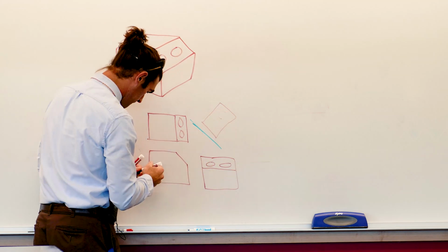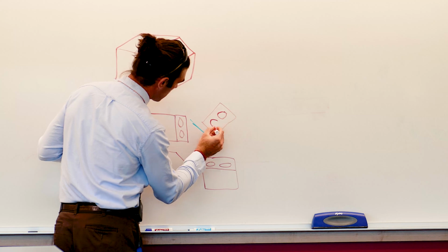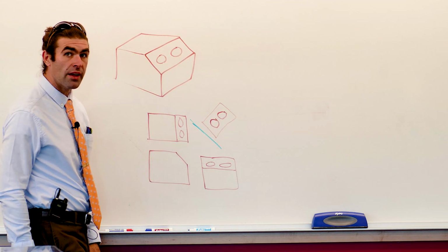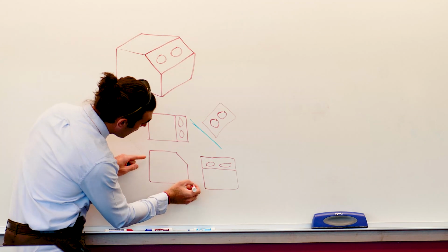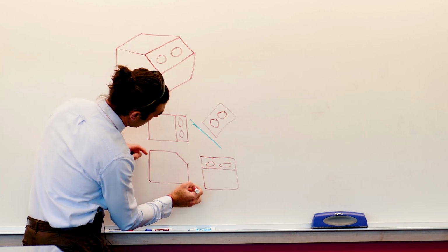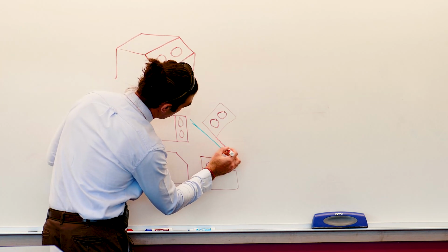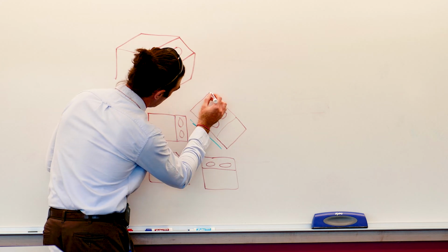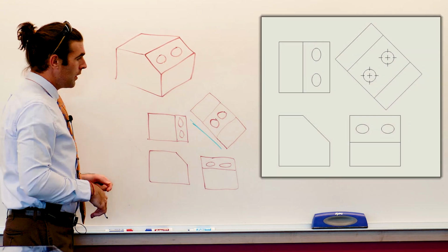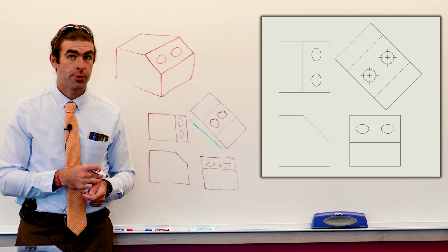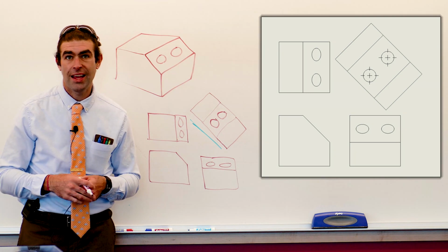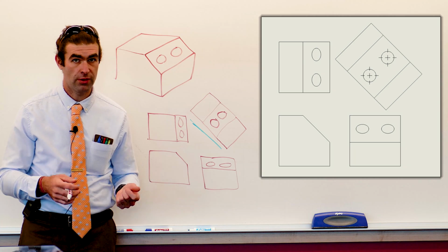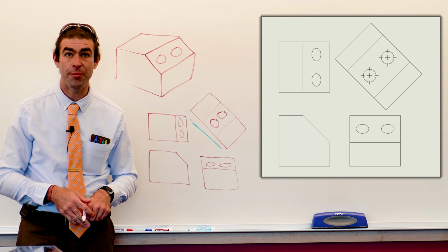The holes are going to appear in true size and shape. And now we project the rest of the part. So if you follow this over, the part will look something like this. Right? Now I'm not using projector lines because you basically never have to do this by hand unless you're sketching. It's super easy to do. The computer does all this automatically.